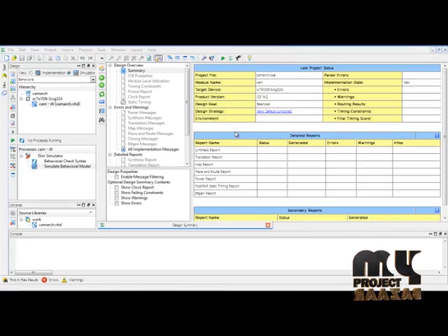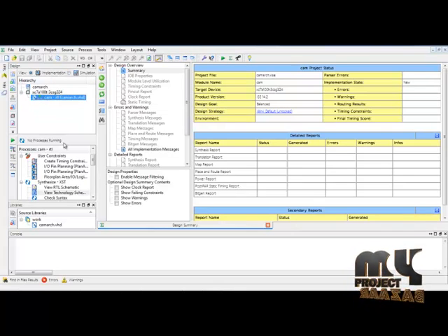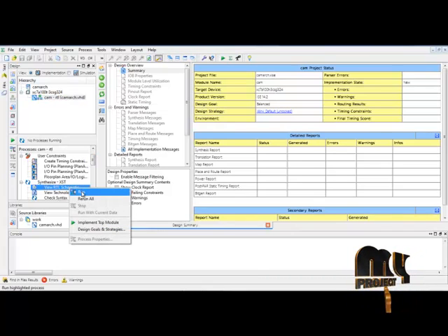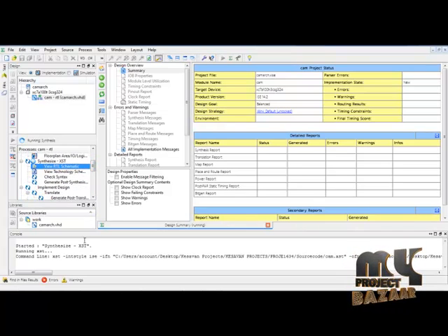Now I am going to explain the running procedure of our project. Now just open the cam.vhd file. After that, I first use the RTL schematic diagram by selecting the implementation radio button and then run view RTL schematic by right clicking it and clicking the run option. This will first check the errors and warnings in the console window. If there are any errors or warnings, they will be displayed in the console window.